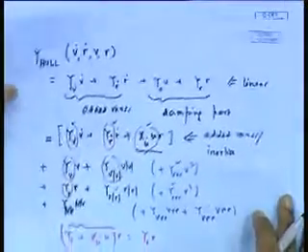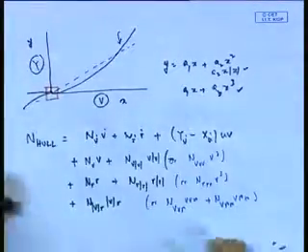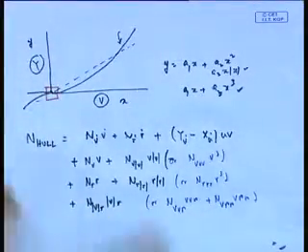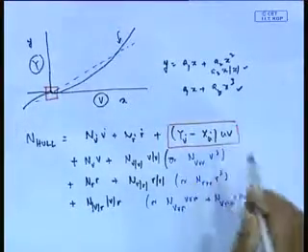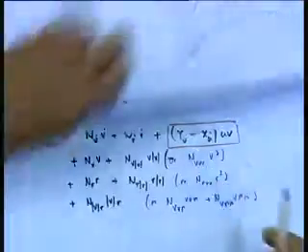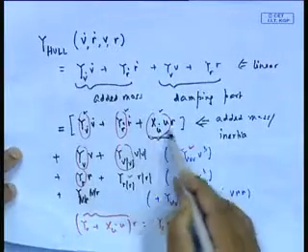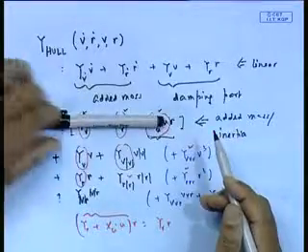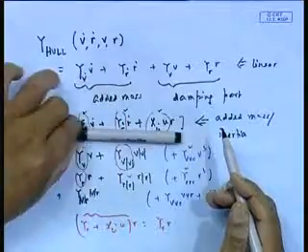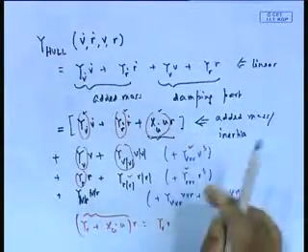See, if you look at this, these are exactly the same, but the only difference in this case is one term, basically this one, the added mass term. This additional part came, this value X u dot u. Now, X u dot is the surge added mass in the forward direction. The ship is here, the added mass in this direction is very small, you can even neglect it.